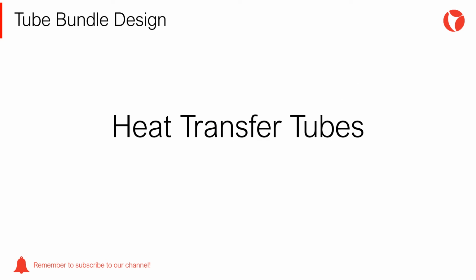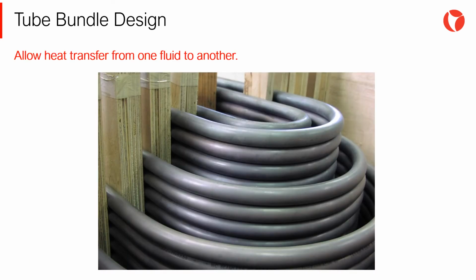In this section, we will cover the design and calculation of heat transfer tubes, cylindrical elements similar to a pipe. The design of transfer tubes is critical to the exchanger's efficiency. This is due to the fact that the fluids interchanging heat circulate at both sides of the tube, internally and externally.